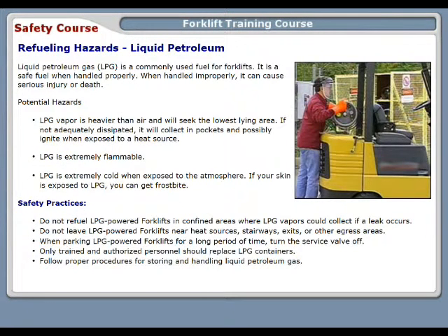Be sure to understand the refueling hazards associated with liquid petroleum. Liquid petroleum gas, or LPG, is commonly used as a fuel for forklifts. It's a safe fuel when handled properly. When handled improperly, it can cause serious injury or death. Potential hazards include: LP gas vapor is heavier than air and will seek the lowest lying area. If not adequately dissipated, it will collect in pockets and possibly ignite when exposed to a heat source.